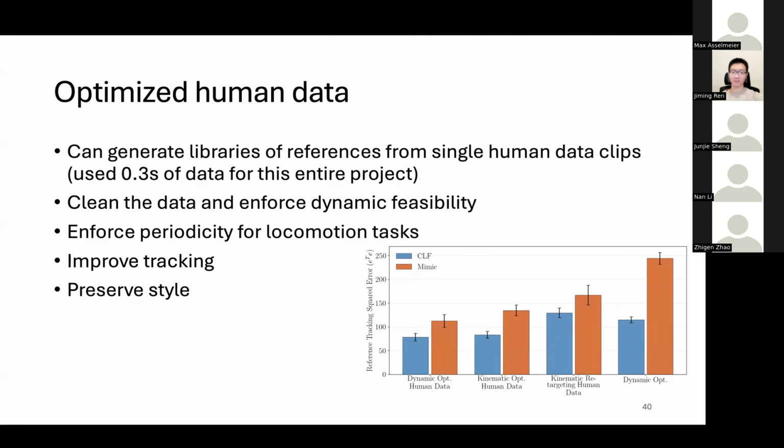Yeah, another great question. I could not currently get a walking and running policy even in the same policy, which I was surprised about because I thought it'd be kind of free to do that. You've got to keep in mind that in the observation, there's no reference. So I think potentially there's a representation learning limit we're hitting here, where the neural network has a hard time understanding that it's almost a discrete change when you go from running to walking. I think it has a hard time getting this difference just based on the velocity change command. So I think it's possible, but this is future work, and it's something I'm very interested in trying to solve.